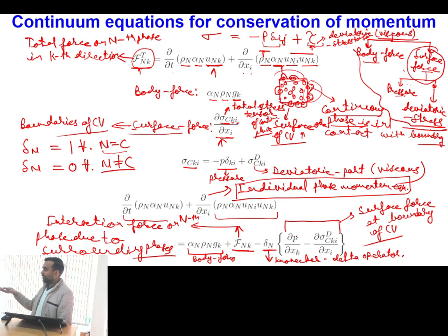In a fundamental way, pressure is again a tensor quantity because it requires a surface and it has direction. But one special nature of pressure is that it always has a uniform value around the fluid particle in all directions, and it has a unique direction, that it always acts normal to the boundary.